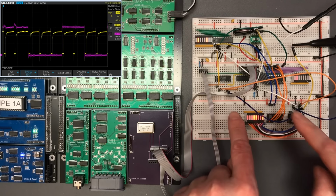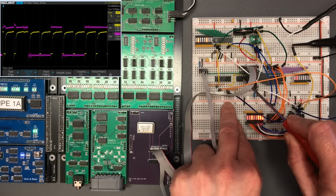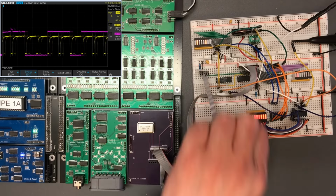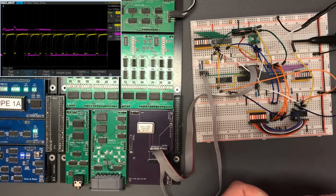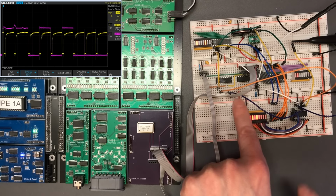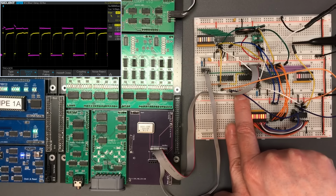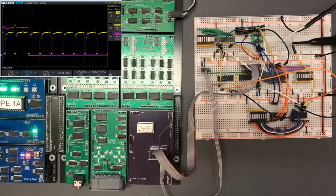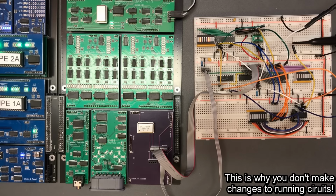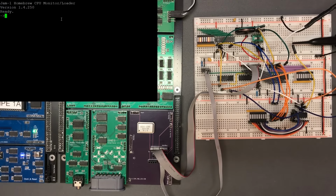So, time to make a fundamental change to the circuit. This latch chip is currently responding to a read request from the I/O lines, and let's pull that signal out. That's active low. So if okay, now I've just broken everything there because I let the line float and that was forcing data onto the main bus. So my CPU has stalled out completely. Let's reset that. Okay, so that's working again.